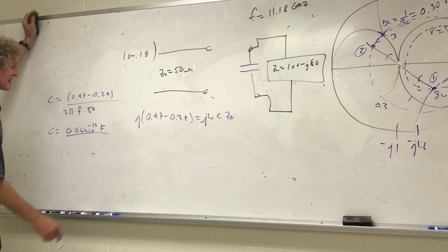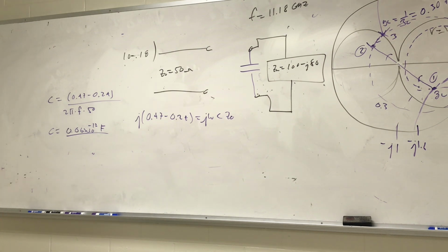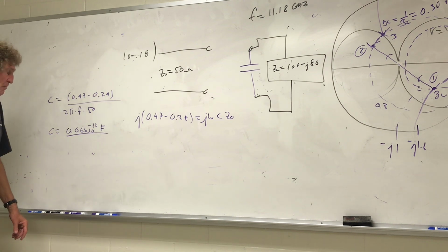All right, now at that level, a piece of wire in length probably changes more than that, just a small piece. We're talking about a capacitance that's not really feasible at this point. There are other ways to do this. Are you with me on this, class? It's so small. One way you can get around that, though at this level, is capacitors in series. If they're all the same value, you divide by the number to find total capacitance, right? So you could take 10 capacitors of 0.6 picofarads, put them in series, and you would technically have 0.06 picofarads. Do y'all follow me?